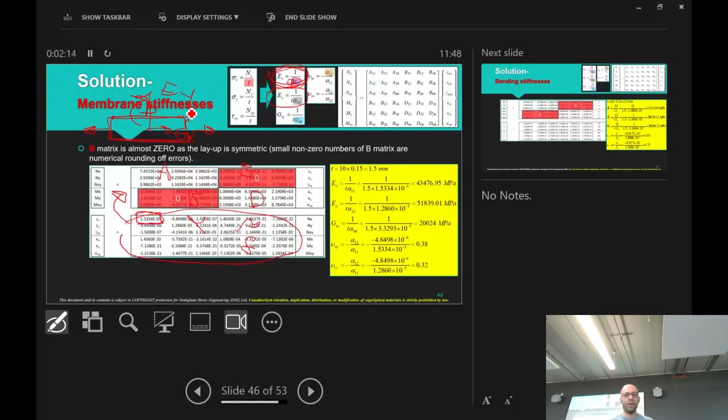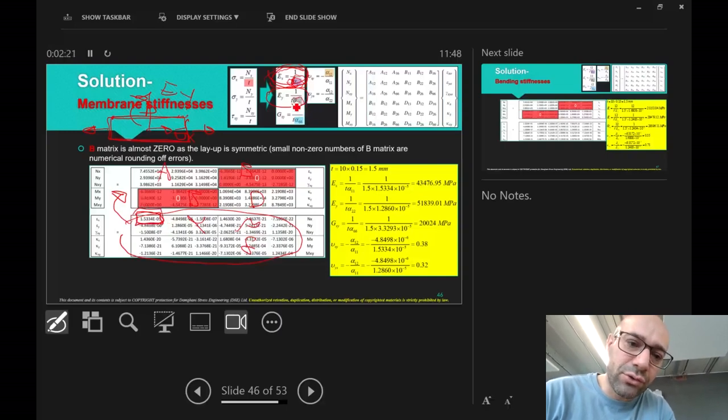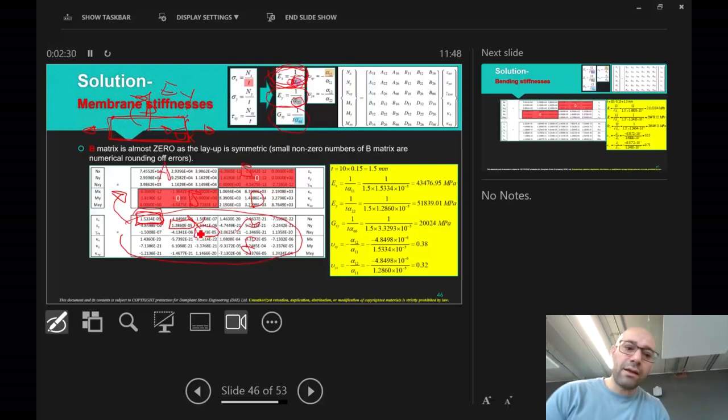Simple as that. So the formulation is: alpha 11, as you see, is that component. EY comes from alpha 22, which is this component. And the shear modulus of that plate comes from alpha 66, which is this component. But here's a delicate point for composites. This EX and EY and GXY that we obtained is associated with membrane loading, which means inside the plane of the composite.